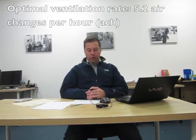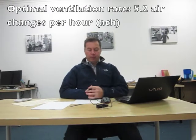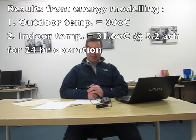From trial and error, we found that the optimal ventilation rate for the building would be 5.2 air changes per hour. And the results show that at 5.2 air changes per hour, if we ran the fans for 24 hours on a 30-degree day, we would get an internal temperature of 31.6 degrees.